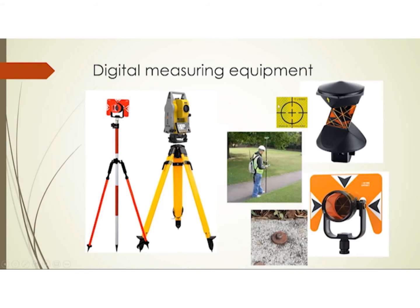And these reflector targets can be placed on the elevations of buildings, again as a known point or as a control point. And for those buildings that are wobbling in my uncle's definition, as in moving, carrying out the survey again at a later date using those same control points would show that the measurement of the building has varied since the previous measurement, and would show that movement has occurred.